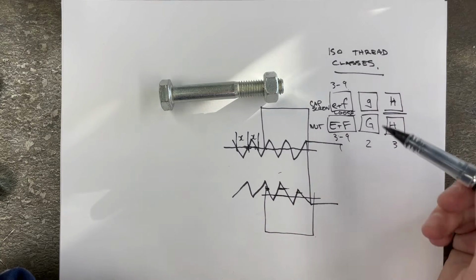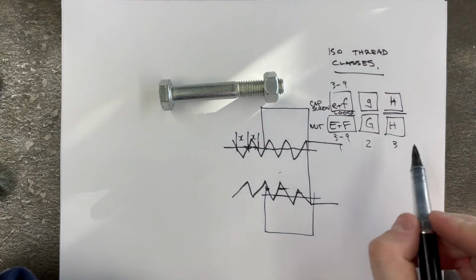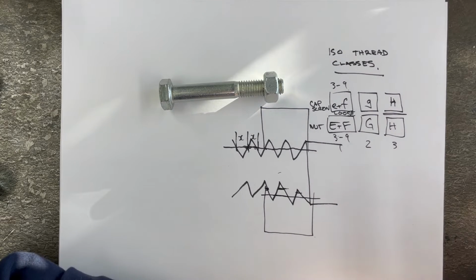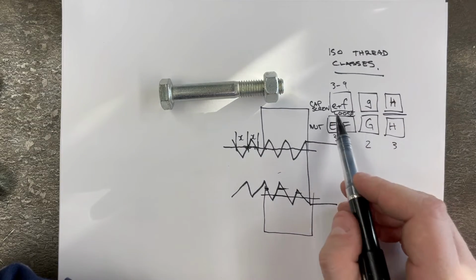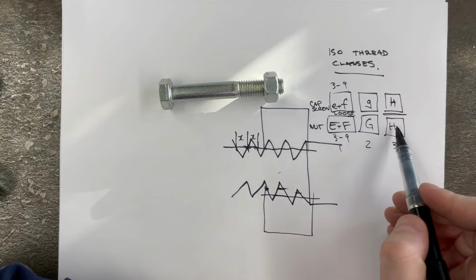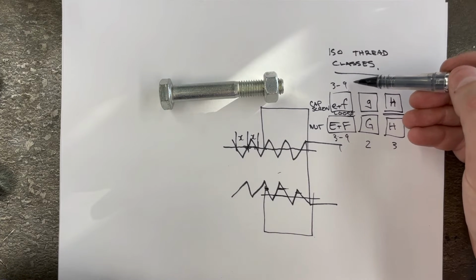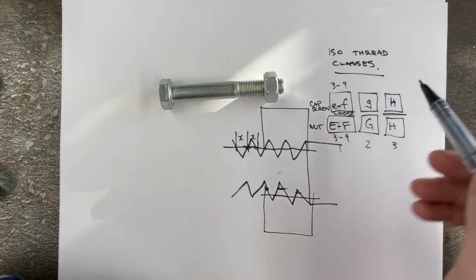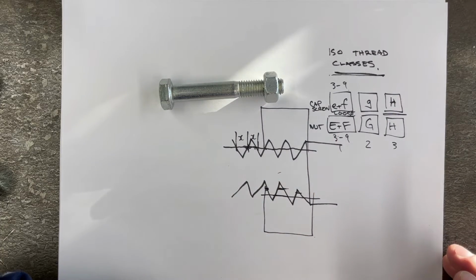And the idea is that some fasteners require that precision type of interference fit to stop the fastener from coming loose. So just understand that ISO classes have these different positions, and they also have these different tolerance grades, and the positions and the grades give you your class.